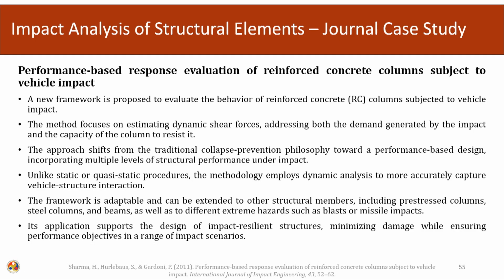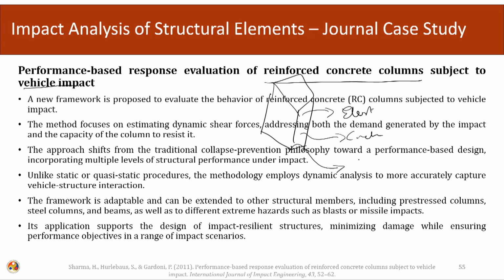Let us look into one case study where we are dealing with performance based response evaluation of reinforced concrete column subject to vehicle impact. Here we have reinforced concrete columns, which will be subjected to vehicular impact. Performance based response means that we are going to fix what type of performance we are trying to expect. Either we are expecting elastic only response, cracking in the system, that the system has crushed, or whether it is going to fail in any other mode.